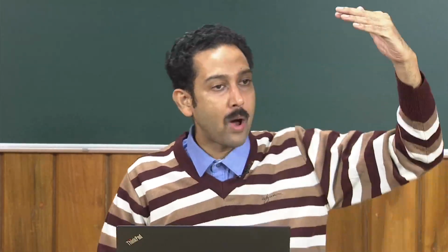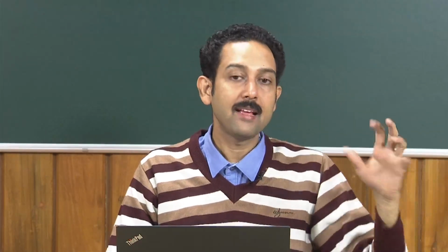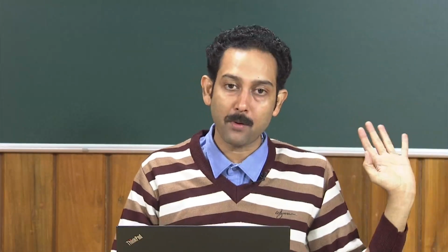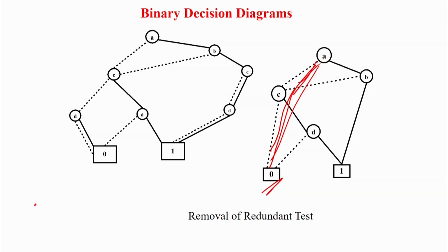So what is the step? On one side we have a state machine, which is exponential, then we have temporal formulas like CTL, LTL, and we do model checking on the graph. That is a very complex problem if the number of state variables is large. On the other side, we will not even go for the state modeling; we will directly represent the state variables or the finite state machine in terms of BDDs, and as already shown, it will be an extremely compact representation of the whole state enumeration. Then you can have very big circuits or systems represented symbolically in terms of BDD, and you do not explicitly represent them in terms of state based modeling.